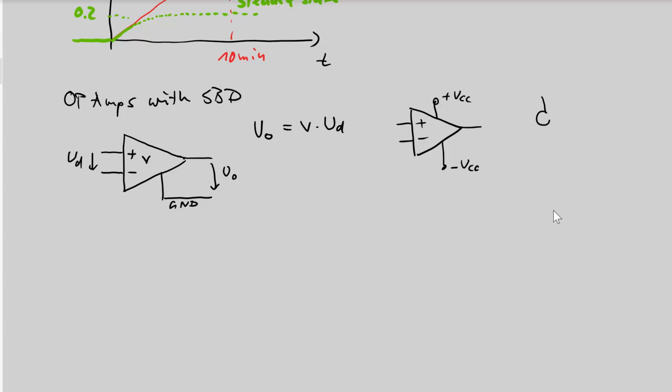And in our application, we need 2 voltage sources, one for the negative and one for the positive, and the double power supply is grounded in the middle. Now this is plus 15 volt, this is negative 15 volt, and the connection between the 2 power supplies is a real ground. So these 2 batteries or 2 power supplies deliver my ground pin. So we can say this is a virtual ground in my system.